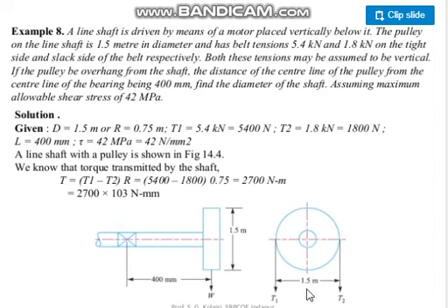Now actually the motor pulley will be a smaller pulley, and the belt will be going like this. But for simplification's sake, otherwise you will have to take values of angle of overlap. We can say angle of overlap is 180 degrees if the belts are straight like this.